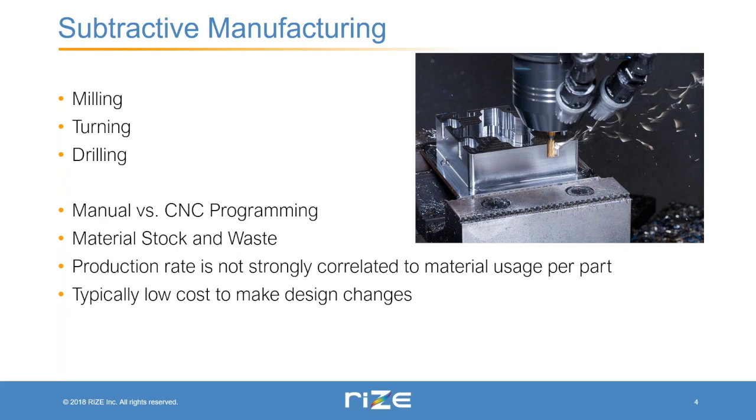So it's often best to design subtractive manufacturing products to not need a lot of material to be removed. So they'll often be designed to be more bulky. Whereas if you were to mill the type of part that is more designed for 3D printing, you could find that there is a lot of waste material due to the amount that's being removed from the starting block.